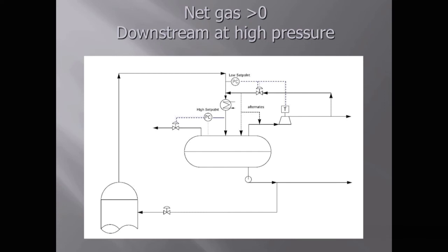Now, if there is a chance of pressure going up beyond the set limits, excessive gas coming up, apart from the normal pressure control, we have another pressure control which is set at a slightly higher pressure, which will release the gas probably to flare. So we have a safety mechanism attached. It's a normal pressure control with turbine speed. It's a split range control plus an added precaution of a relieving control valve.